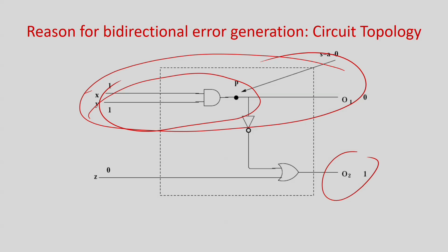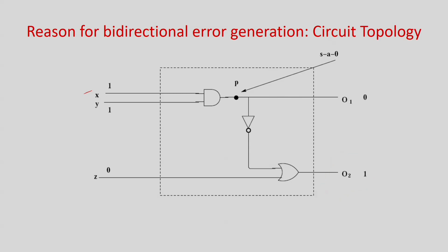But people have found out that, because people are trying to find different solutions for online testing, if you have the liberty that for any given output you have no common sharing of gates between two outputs, then you can simply use parity codes and you will have online fault tolerance. But then the circuit size becomes extremely high, and no designer accepted it, because I have made a very small circuit, very optimized in area, and for testing you are extremely blowing it up. So basically the term is called intrusive design.